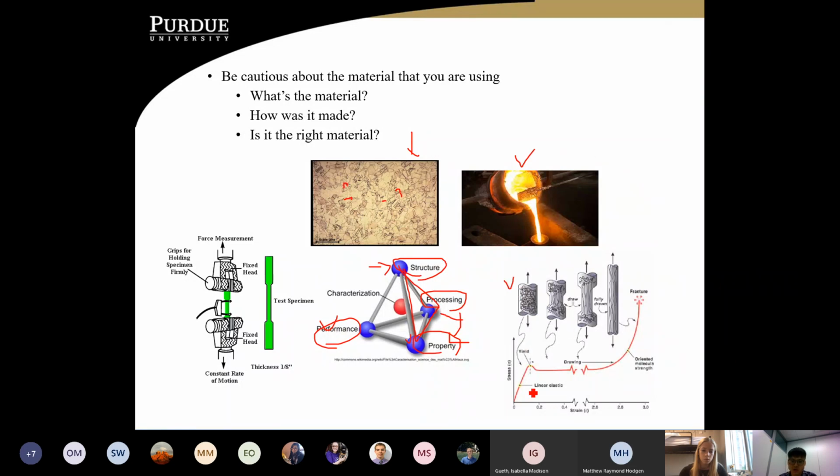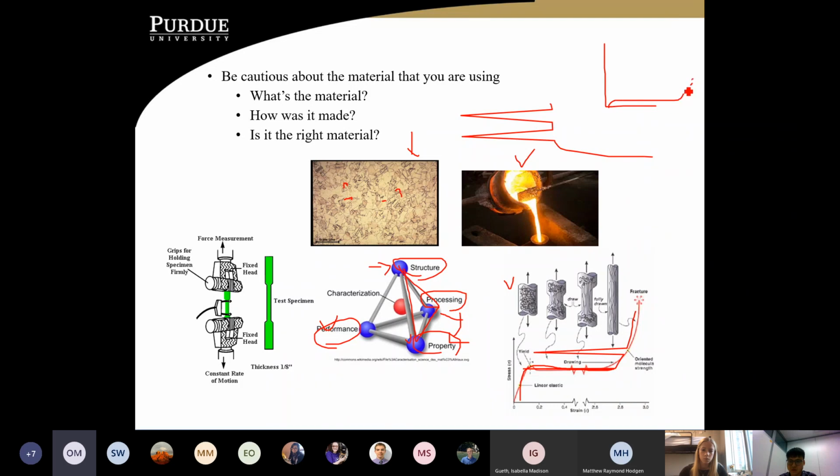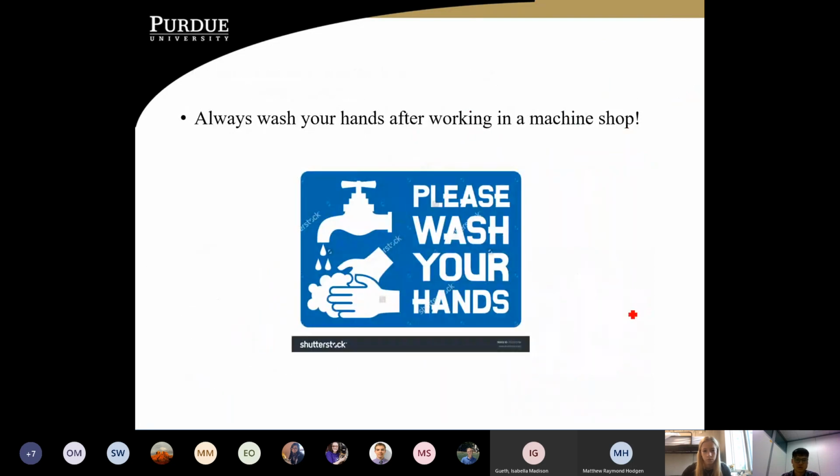And then, all right, this is the polymer. This is what I drew at the beginning, right? So you have a structure like this. If you look at the structure, you see these are the filaments, like the fibrils inside the polymer. If you don't know it, it's totally okay. But you can at least see that it's sort of different, right? When you start pulling, these lines get aligned. That's why at the end here it spikes up, because when these lines are all aligned, it has a higher strength to resist pulling. If you're interested, I'm more than happy to talk to you more about it later.